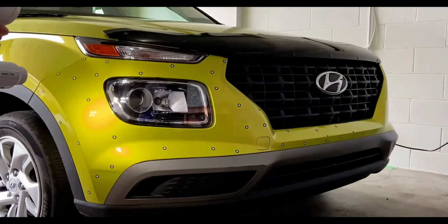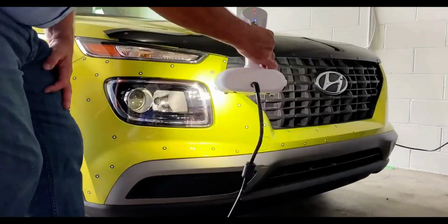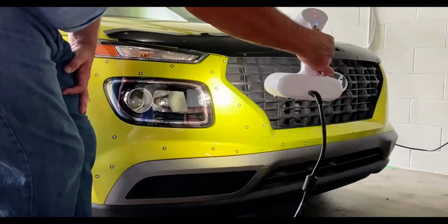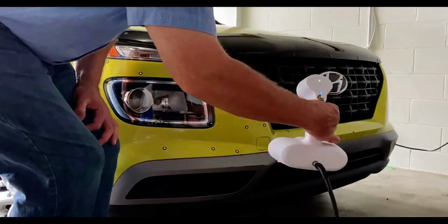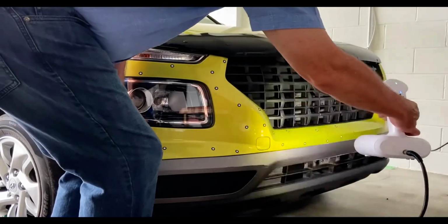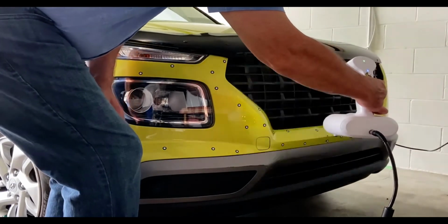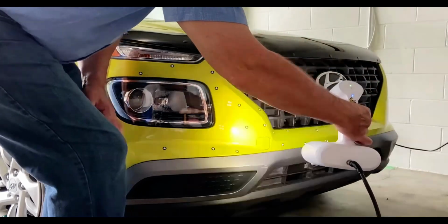Now we're just going to go over and scan some of the areas again. You want to scan in such a way that you do not have a resulting scan that has holes or misses detail because you've scanned too fast. Once again, you orbit about 30 centimeters from the surface, keep the scanner in constant motion, and you should get